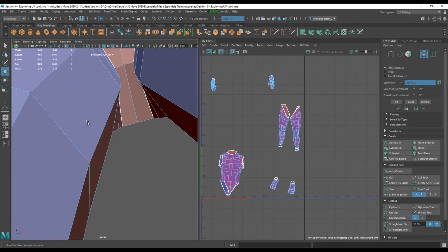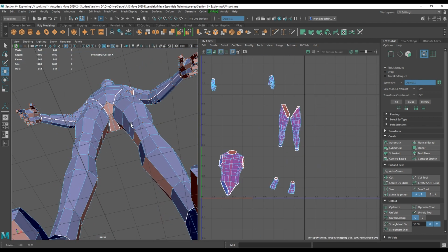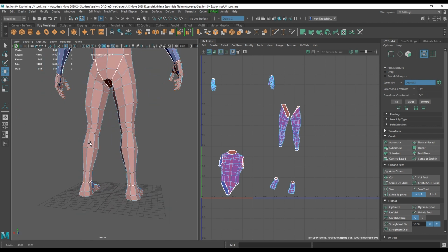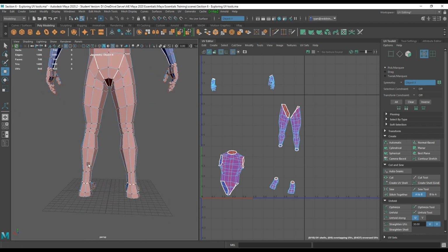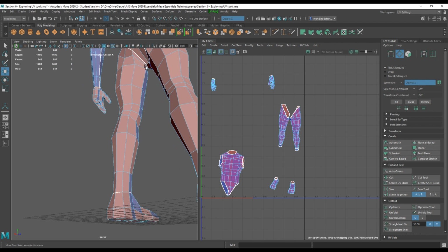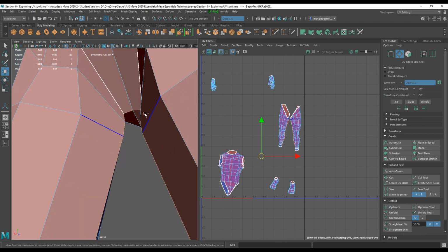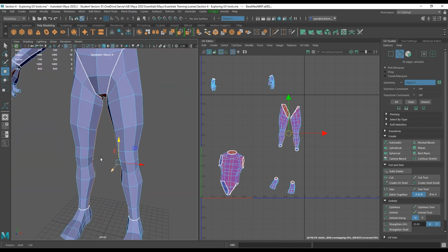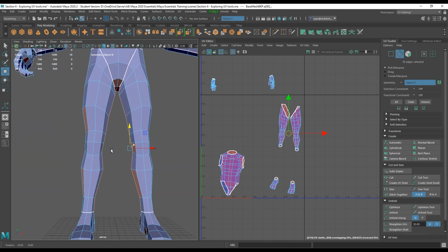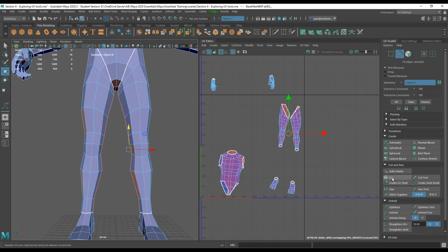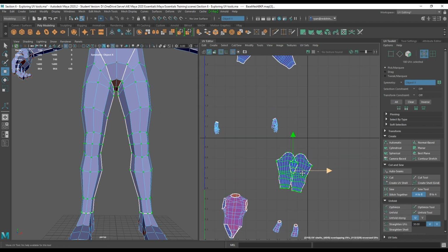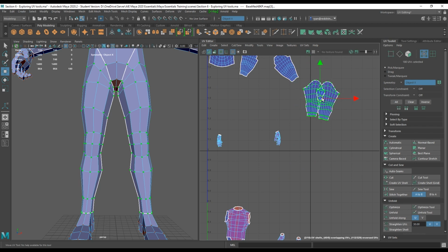I can do the same with the legs. So the legs need to also, normally what we do is we hide the seam lines on the back or potentially in the center of the leg here, because that is also an ideal space, and very rarely would a camera be in this angle of a character. So putting the seam line for the legs in here is one of the better options. So I'm going to go cut, right click UVs, double click and unfold. Got my legs done. I'll just move them out of the space here.